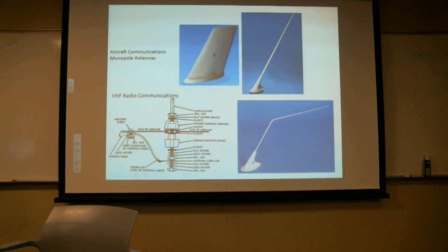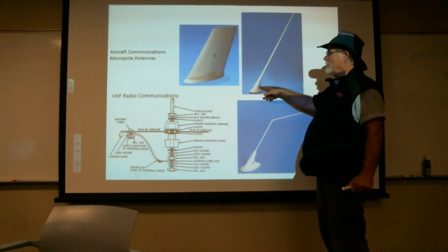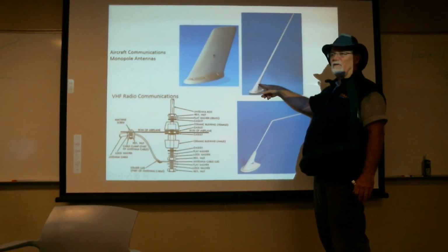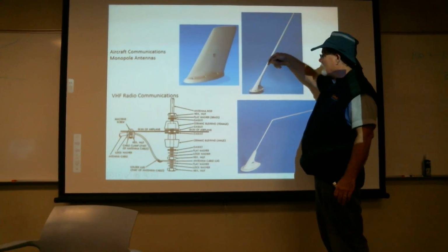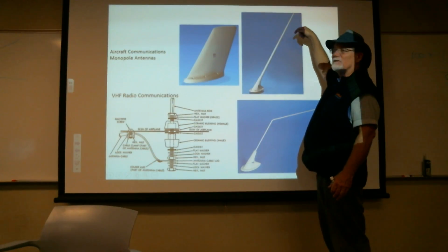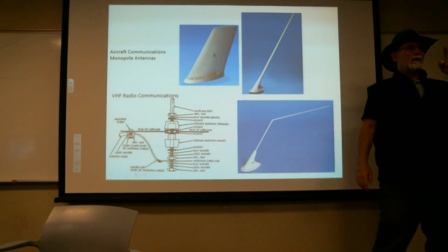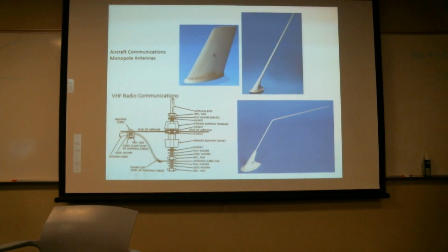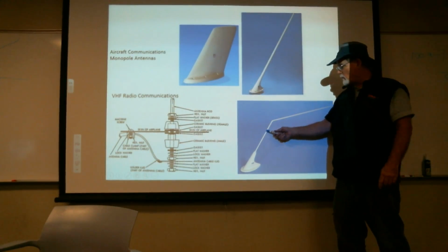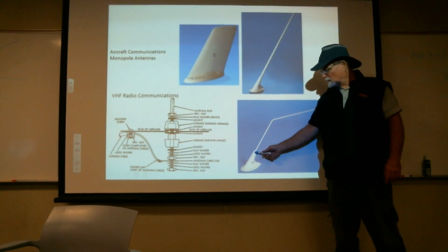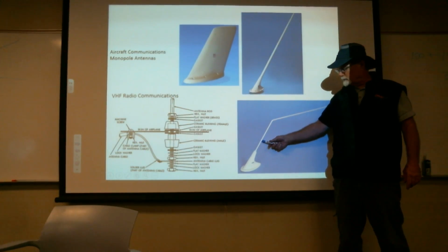Or, for example, like this one, the antenna has to be that long. There's nothing that says it has to be perfectly straight. So I can make it that long by doing a spiral wrap inside this little composite tube, and then just curlicue it some. So a lot of the smaller radios with the little flex biscuit on the end of it, that's what they've done. They've just taken the wire and made a curlicue out of it. Does that interfere or reduce the strength a little bit? Yeah, but those things weren't made to be long range anyways. This will work. Here's another one where it's a straight conductor, and that's probably still a little too short as well.